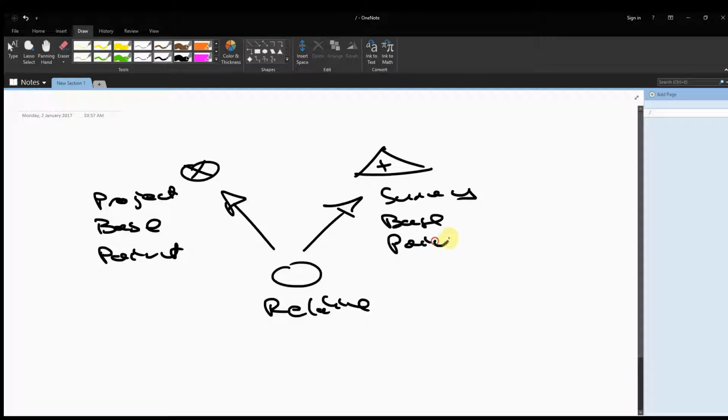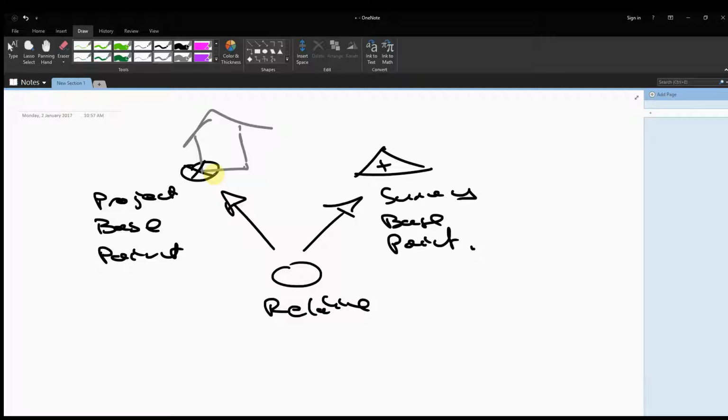base point. All the geometry in Revit, let's make it gray like it would be concrete, is actually stitched to our project base point. When we model our geometry, I have sometimes the feeling that it reverts back to our project base point, and so when we move our project base point, all the geometry moves with it. Also all the imports, anything else moves with this, which is actually good.